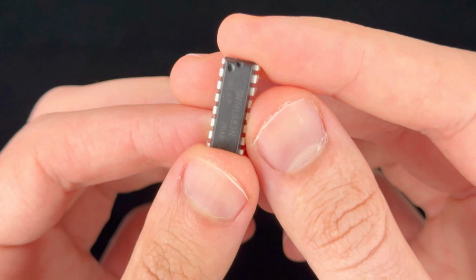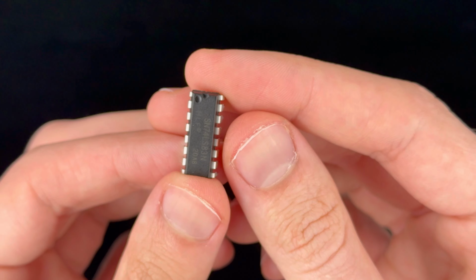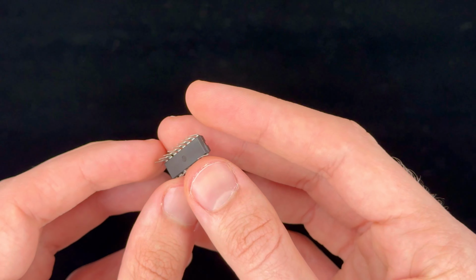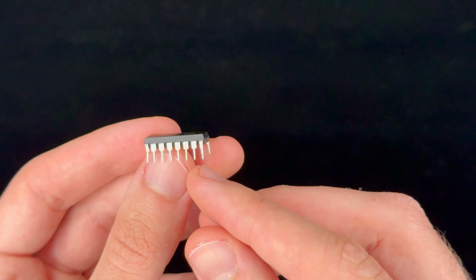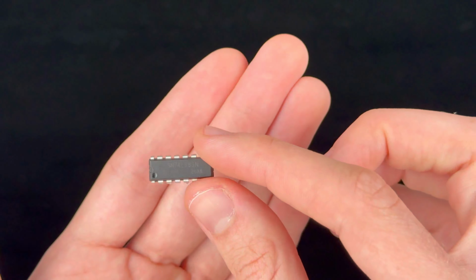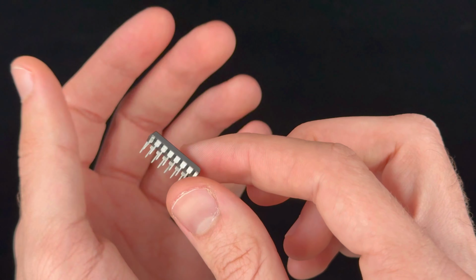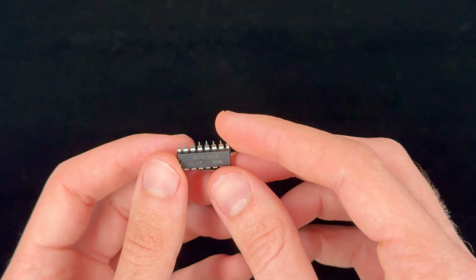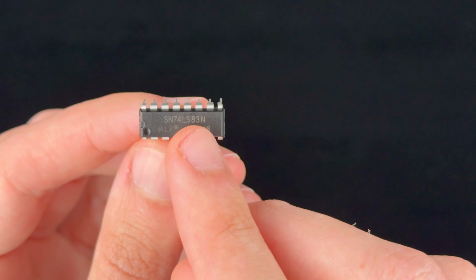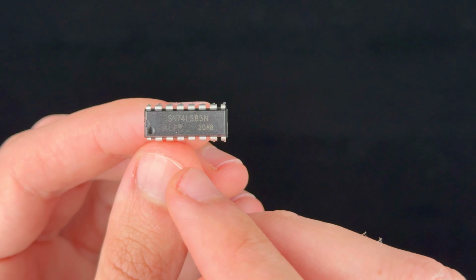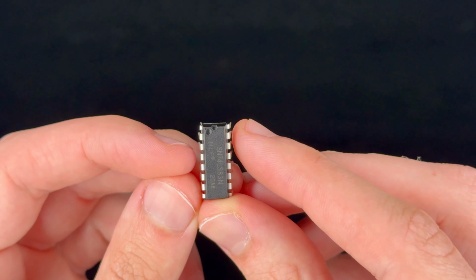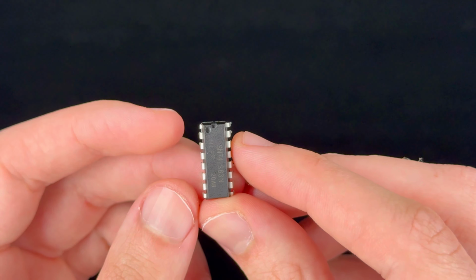Each IC has a unique model number. It is used to identify the IC so we know what exactly we're dealing with. If you look up the model number on Google, you'll find a data sheet for the IC. The data sheet will show you the function of the IC, how it is connected internally, what each pin represents, how to connect them, and more. This IC I'm holding is a 4-bit binary full adder, and its model number is SN74LS83N. As the name suggests, it adds two 4-bit binary numbers and generates their summation.